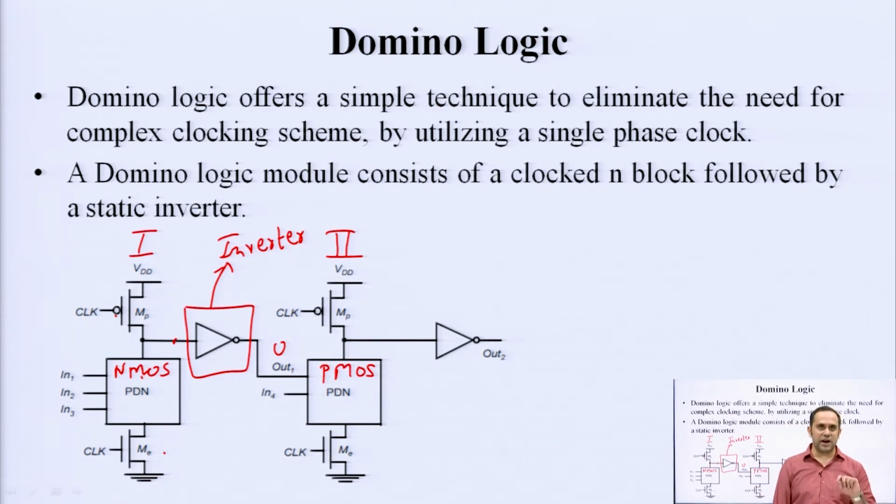Okay. So, this is slightly different from the standard dynamic CMOS circuit, where by default after pre-charging you have 1 present at the output. Either you hold that 1 or you make a transition from 1 to 0. But here in this case, we are connecting an inverter to allow cascading connection, such that after your pre-charge has ended, every input of the successive stage after the first stage is actually having a 0, okay, after pre-charging.